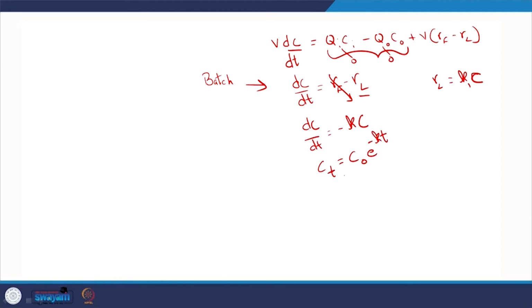So, concentration at time t, and what do we have? We know that C initial or C naught, here it is not C out, let me say C at time equal to 0, we know is 10 milligram per liter, and C at time equal to 30 minutes is equal to what now? I think it was 2 milligram per liter, right. Typically we need to bother about the units, but here as you can see Ct by C at time equal to 0 is equal to e power minus Kt. We see that the units are cancelling out. So, we do not need to really bother about that.